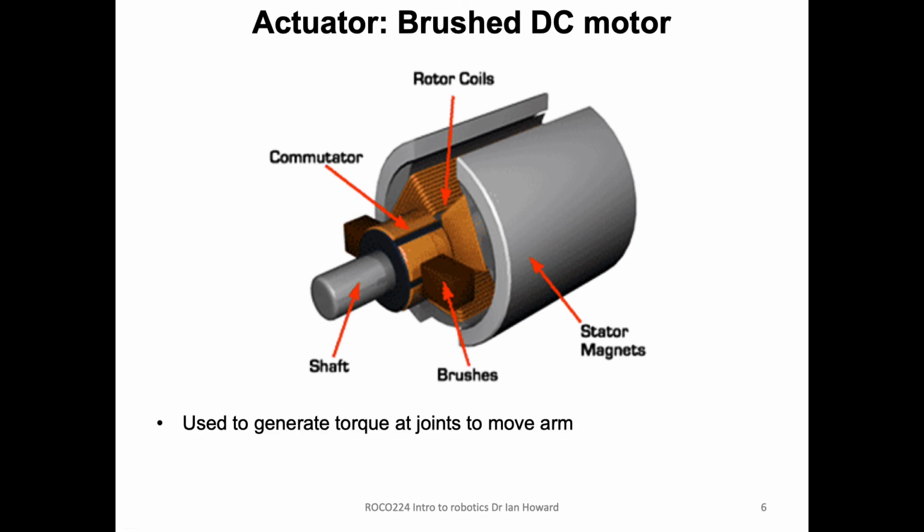So these things obviously are going to be a bit cheaper than the brushless motors, but they are very, very effective. Basically the same kind of principles apply in terms of torque. Generally, we can't use it directly without a gearbox, but they're very, very useful things to use for cheap projects.